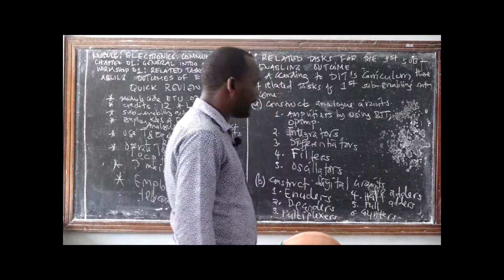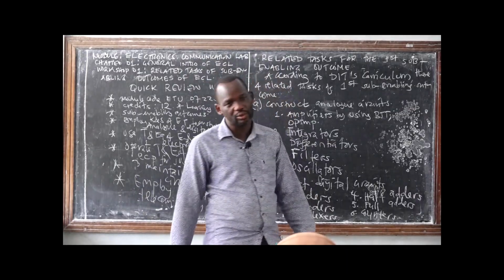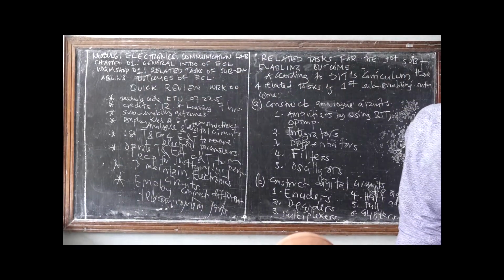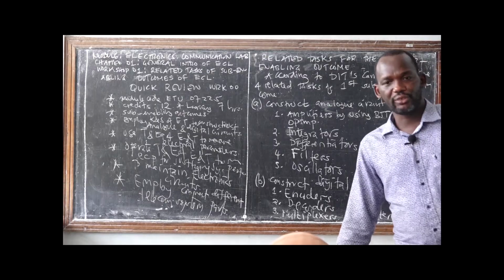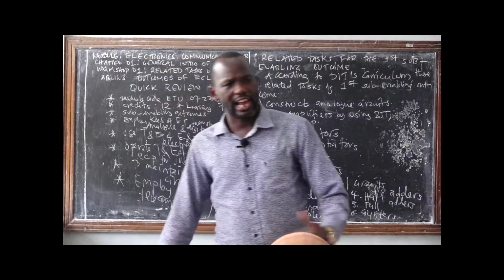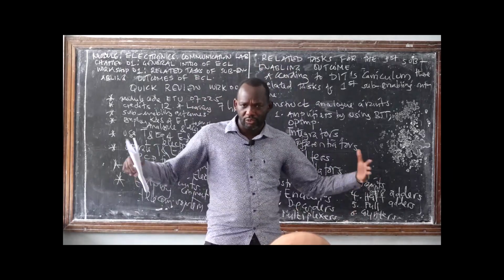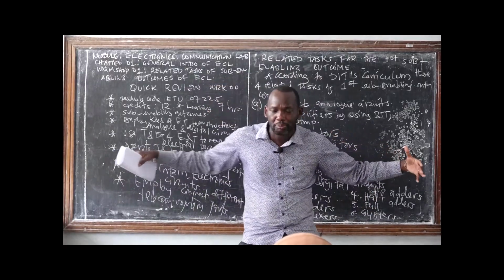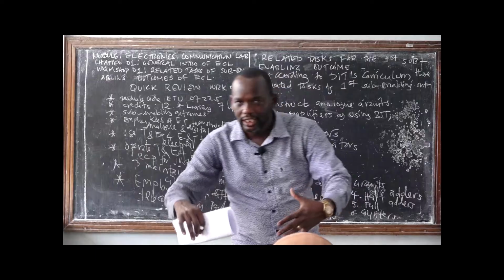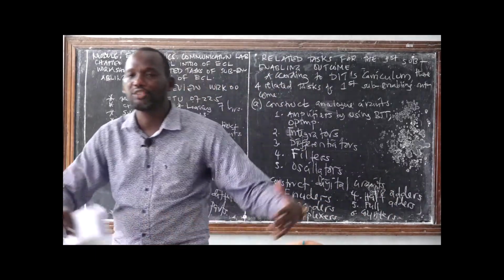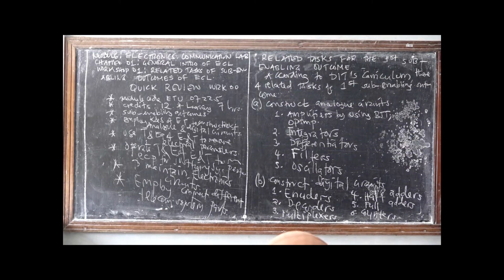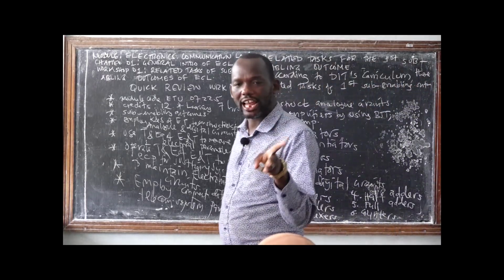Are we together? For instance, this is used in cellular communication. I make a call. I want to call my friend in Mwanza. Then Samandito also wants to call his friend in Geita. Then maybe somebody wants to call his friend in Kagera. So we are using the same network, Vodacom. So we have three calls. Our calls will be encoded and multiplexed, which means they will be combined and transmitted through the Vodacom network from Dar es Salaam to Mwanza. So the multiplexer is the one that receives these three different calls from different callers.